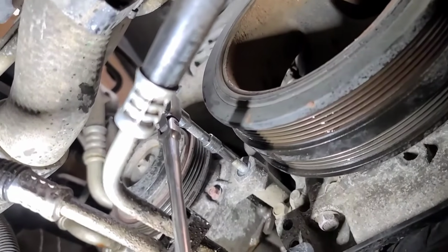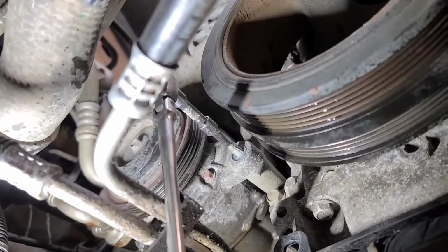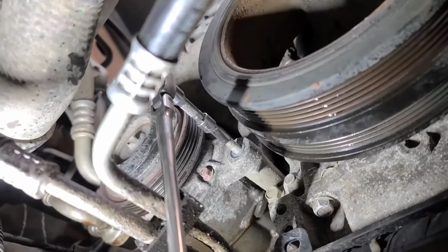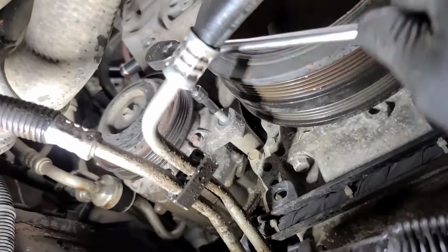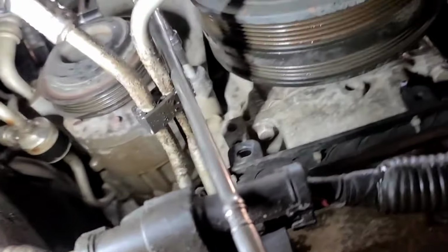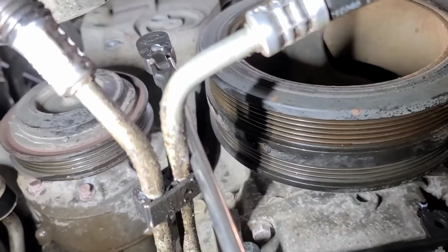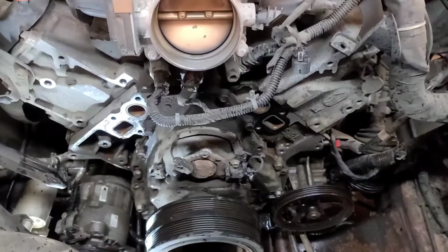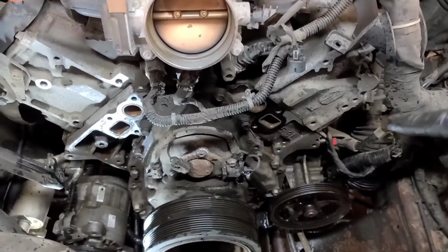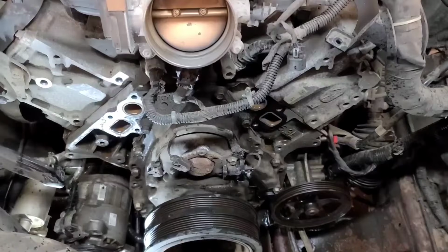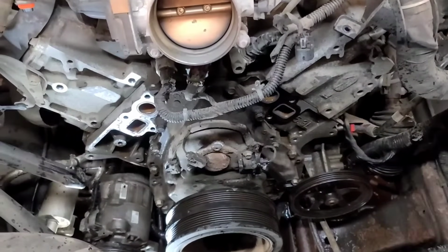So to get the AC compressor moved out of the way, you have to remove that stud. It has a hex on the end. I think it's 6mm or 5mm. So once you remove that stud, then the compressor will slide to the right. That bracket behind it is part of the bracket that holds the alternator on. That has to come off. So there are 7 bolts that hold the water pump on. 3 on the side here on the right side, and 4 on the left side, driver's side. Couple of clips on the harness on the back of the water pump as well.